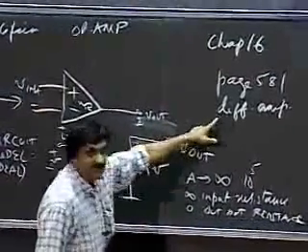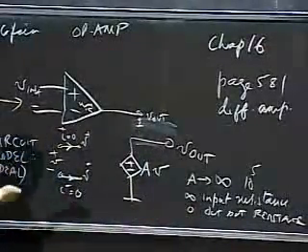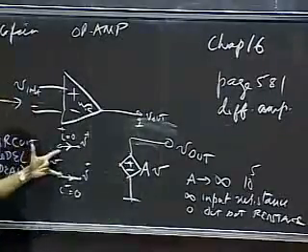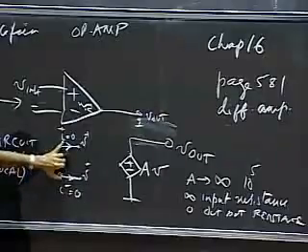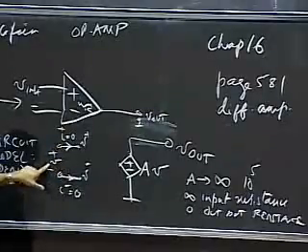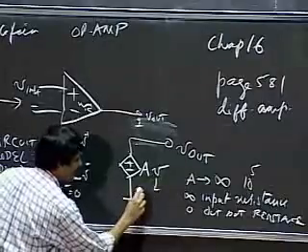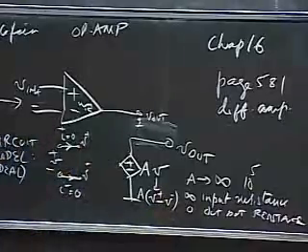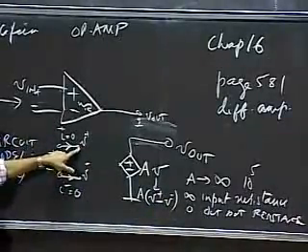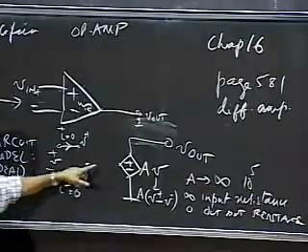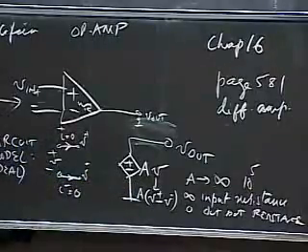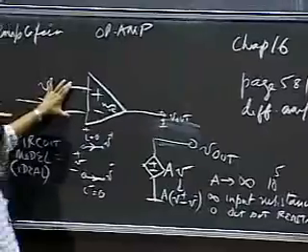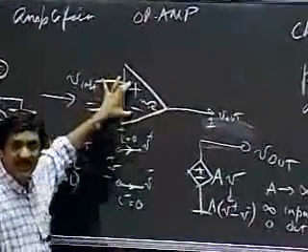And that differential amplifier, as the name implies, amplifies not a single voltage, but a differential voltage. Note that this guy amplifies the voltage difference between these two terminals. That's V here, and V is simply V plus minus V minus. It's the node voltage here minus the node voltage here. That's what's amplified. So it amplifies a difference, and therefore it's called a difference amplifier or a differential amplifier. That input stage is what's inside the op-amp.